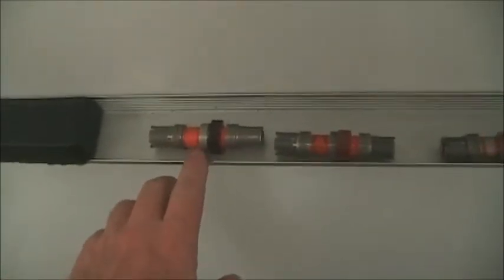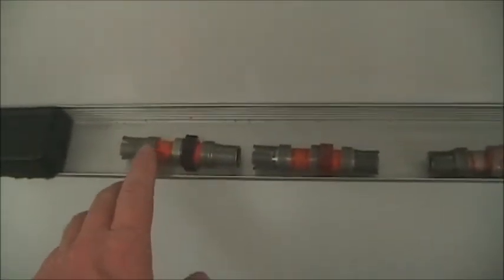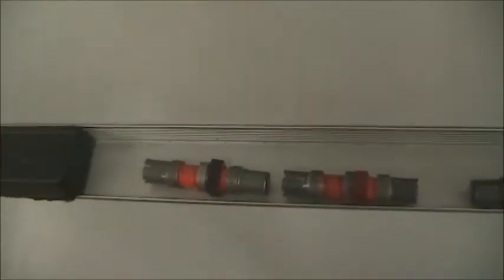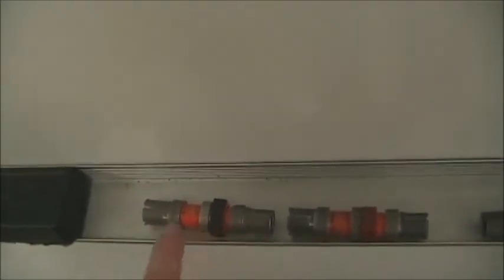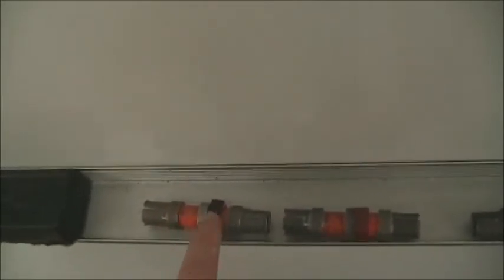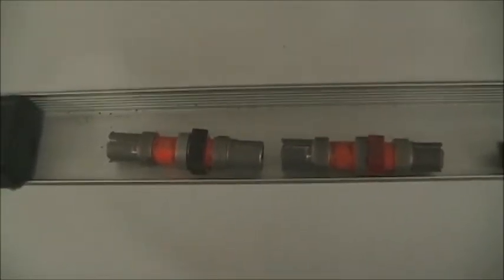So these pads that I'm going to test are actually T pads. If I open this up, you'd find a resistor R1 connected to the center conductor, and this is the outer conductor. They're kind of funny looking resistors because the middle resistor is actually kind of a disc, because it goes from the center conductor to the outer conductor. And then the 2 resistors on the input and output are just in the series path from the center conductor. I probably won't show you that, but I've opened them up before.